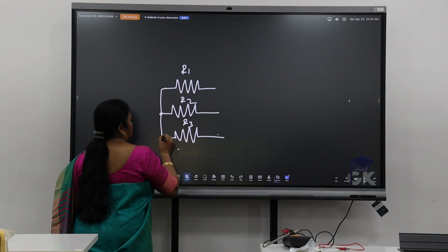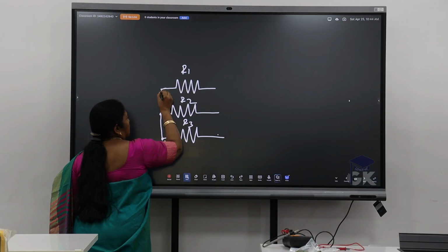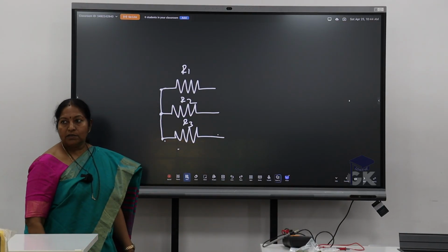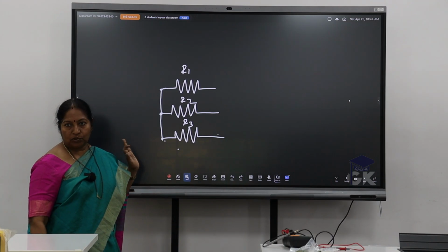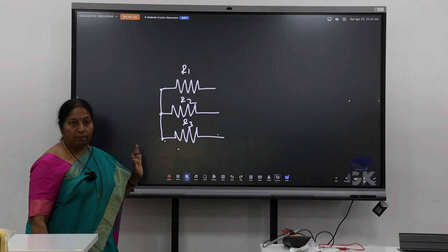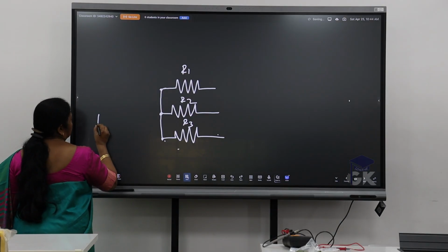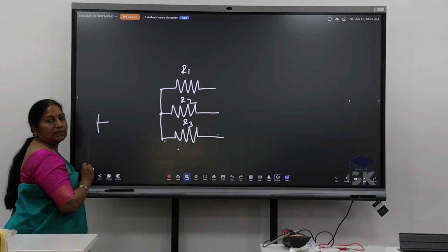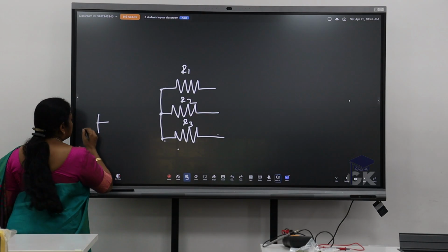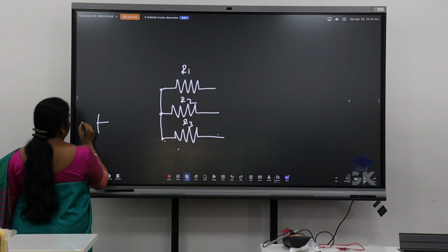So always you should put a dot at the connection, a dark junction point should be shown. So if it is a jumper, that you should learn always. See now this point is there. I just connect like this and this is not connected. Suppose here let me say I have 0 volts.